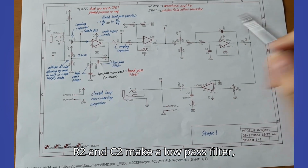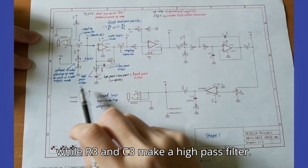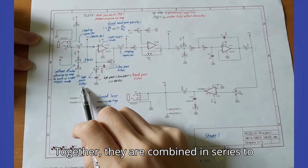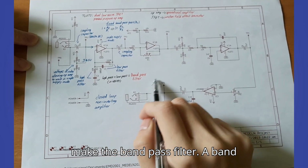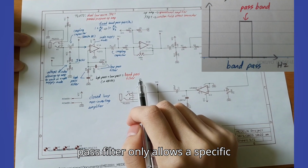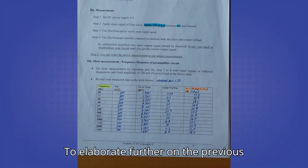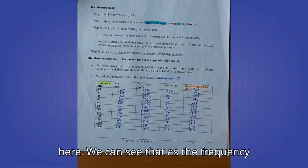R2 and C2 make a low-pass filter, while R3 and C3 make a high-pass filter. Together, they are combined in series to make the bandpass filter. A bandpass filter only allows a specific frequency range to pass through. To elaborate further on the previous sentence, let's take a look at this table here.